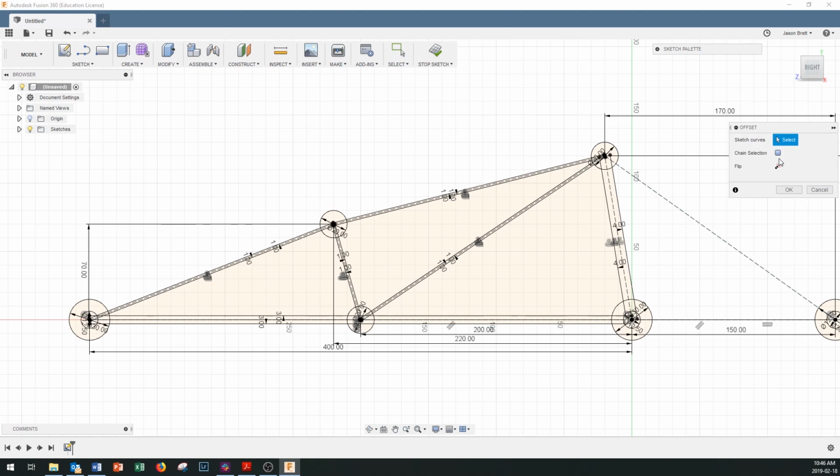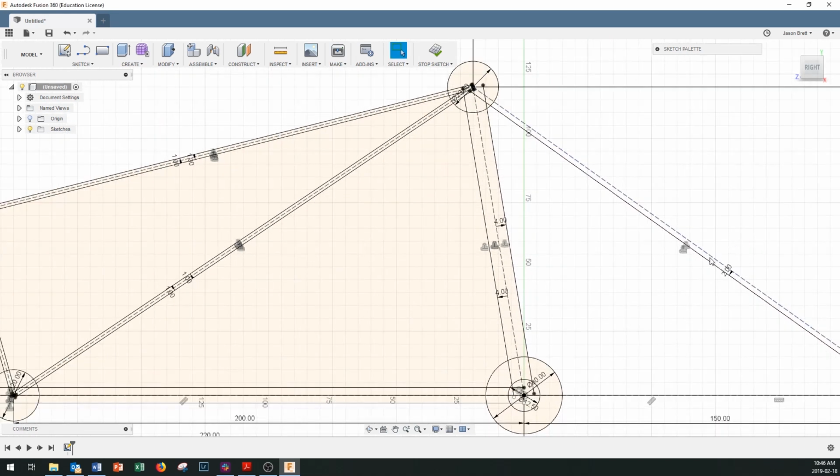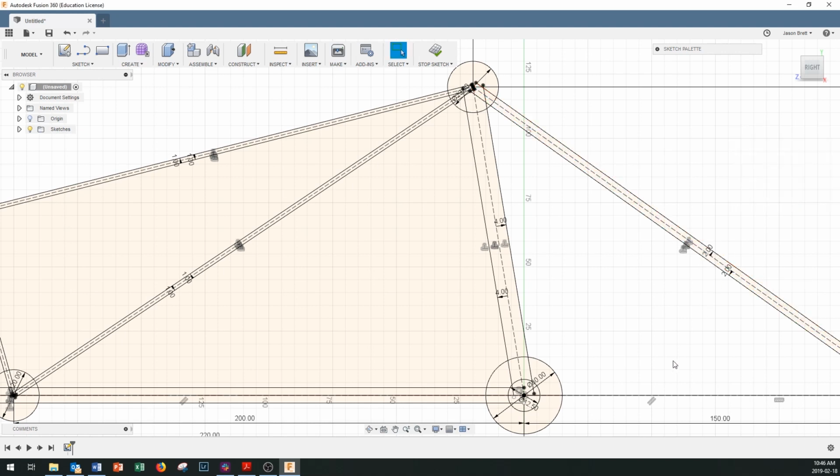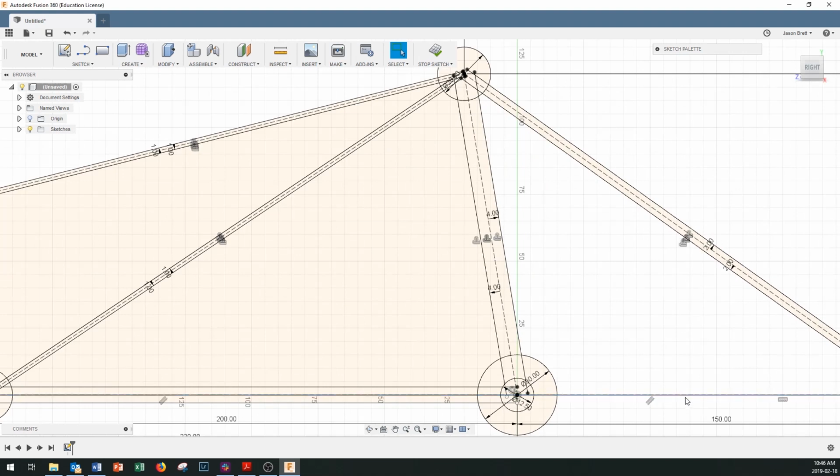And we'll finish up with a fairly narrow section here at the back. This one does get quite a bit of tensile force in it, so let's maybe give it a 2mm offset, and we'll do that again right there. O for offset, flip the direction, 2mm, and down here we'll make it 3 just to keep in with everything else that we've got going along the bottom.